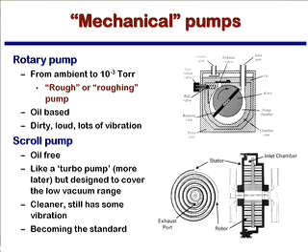But basically, it's just a bunch of rotors that spin around, again much like the roughing pump. They trap air in here, and then by their spinning, the air is forced down through this kind of curlicue, looks like a cinnamon bun, right, and into the output so that they get passed through. And the thing about these is that they are cleaner, they have less vibration, and really they're a better system for microscopy purposes because of this, and are becoming more and more the standard that you buy as you purchase a new TEM, okay?